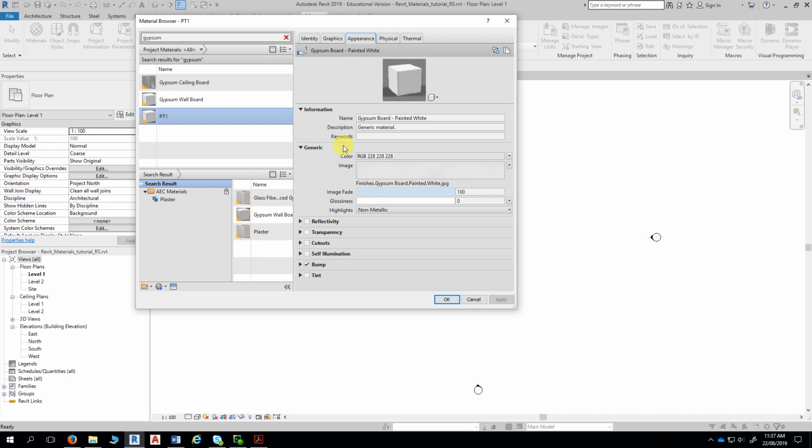Now, the current appearance asset is based on a JPG, which is this white colour. We're not going to use an appearance asset that is using a texture map. We're going to use an appearance asset where we actually plug the RGB value in, and Revit will actually produce the colour artificially, which is perfectly fine. So rather than duplicate, we actually replace the asset.